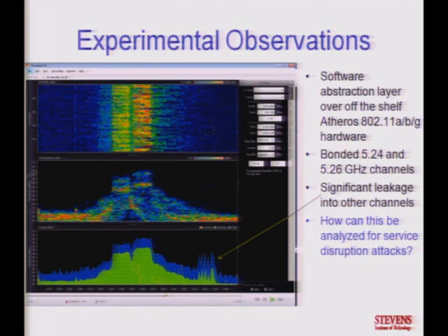And in terms of percentages, I'm not sure how clear this is, that's a good 40 to 50% extra. So it's not a negligible kind of signal we see. And we didn't observe this when the bonding was not there. Initially we even thought that this could be something else, but we found that when we do not bond, this shadow never appears. It's only this picture. And when the bonding takes place, this happens. So there is leakage due to bonding on other channels.